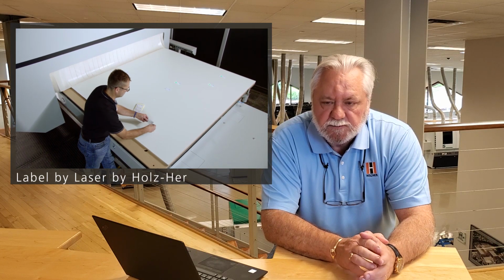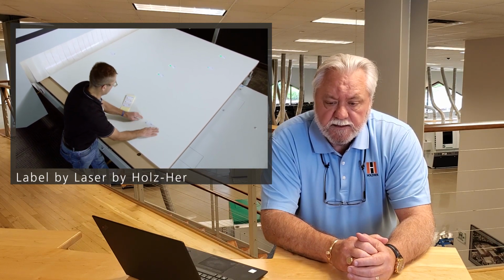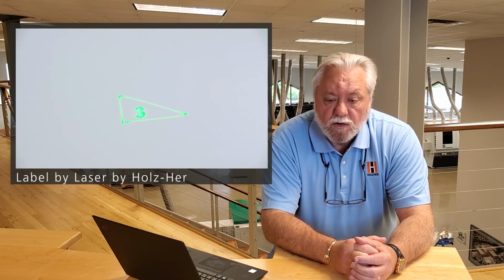Label by Laser. This process allows the sheet to be labeled prior to being machined while the sheet is clean and dust-free. The labeling can be done directly on the machine table or at a labeling station, or directly onto a scissor lift unit. The overhead laser examines the tool path and the drilling location and determines the best place for the label to be located without sustaining any damage. It also projects the orientation of the label as well. The movement of the laser position is accomplished with the handheld remote control unit.